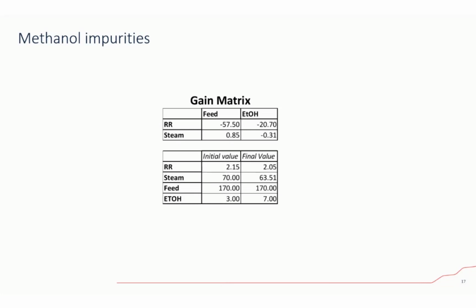But since when you use an automated step testing tool you need to use a seed model, which is not a very accurate model in itself, if you have a lot of interactions, then your automated step testing tool could start struggling. And if on top of that your time to steady state is too long, the tool will try to hold the steps for as close as possible to the time to steady state.